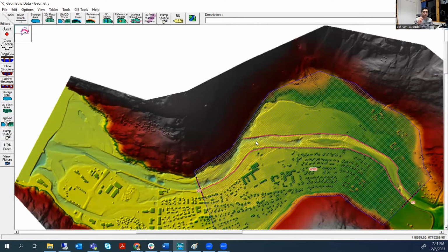It is very, very important, especially when you have another format of the river. You should define a break line at the bottom of your bank and at the top of your bank or floodplain, and one in the middle of the river or the center line of the river. And how to choose the center line, I explained in a previous video for the 1D modeling.